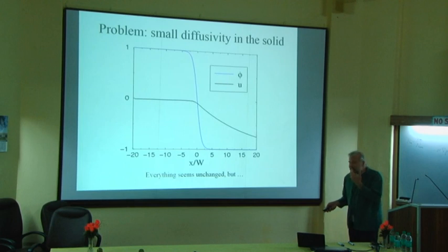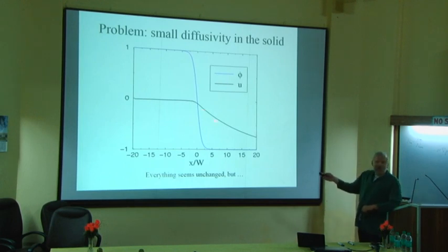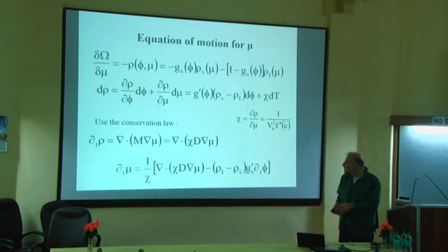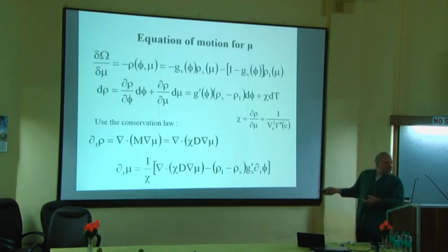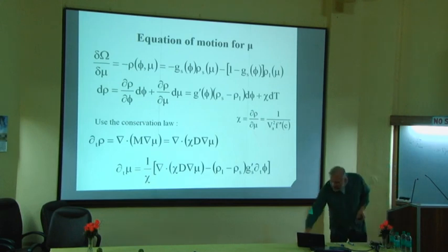And just as yesterday, you see, here I have a gradient in chemical potential, so this drives a solute current. So the solute is evacuated here, and this makes the interface go forward. And inside the interface, this term here will redistribute the solute. So I will have a source term for the chemical potential that is proportional to the difference in the concentration between the two phases. Just like in the thermal case, where I had a source term that was proportional to the latent heat, which is the difference in internal energy between the two phases. Once again, perfect analogy. Okay?